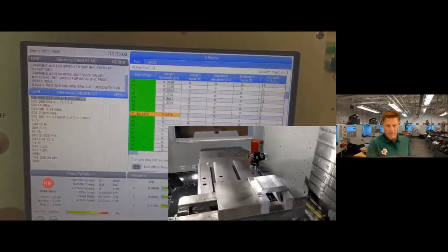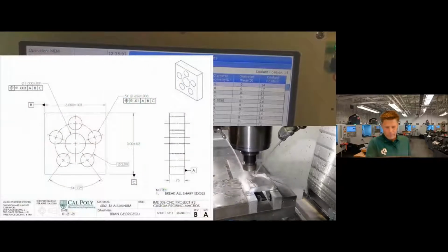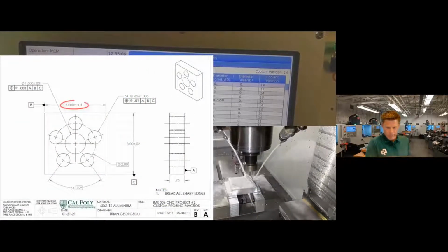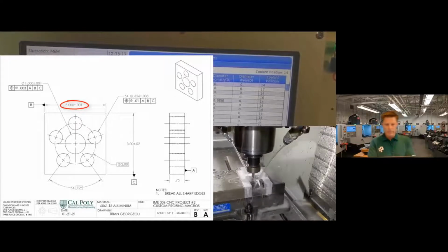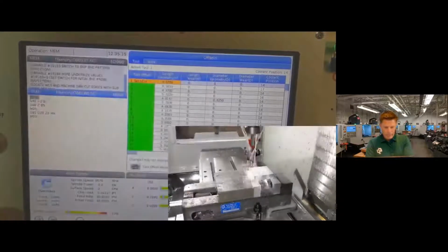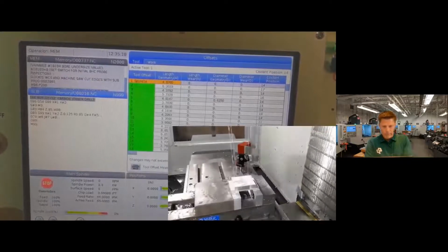Then we're going to grab that 1/2-inch 3-flute carbide end mill and trim up the sides real quick. We have a tight side tolerance there, right? So we have to trim up the sides. The soft jaw is actually relieved a little bit lower than where the part sits. And we're able to mill the sides with the periphery of the cutter.